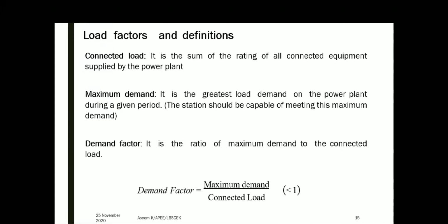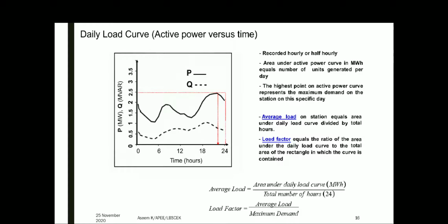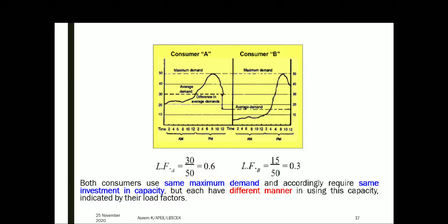Here you can see one of the importance of load factor. This figure is a load curve, that is the load versus time, and from this particular load curve you can find out the average load, that is the area under the load curve divided by the total number of hours, and load factor is average load by maximum demand. Then what is the importance of load factor in a power system?